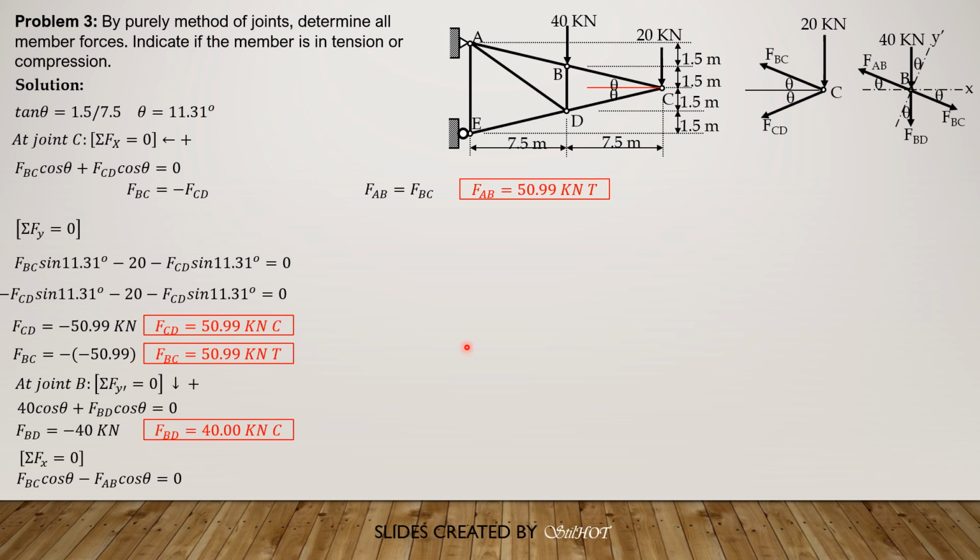So next, we cannot proceed at joint A because there are 1, 2, and the reactions at A not yet known. So we consider the entire system. We sum up moment about A equals 0. There's only one horizontal reaction at E. And these are the reaction forces.